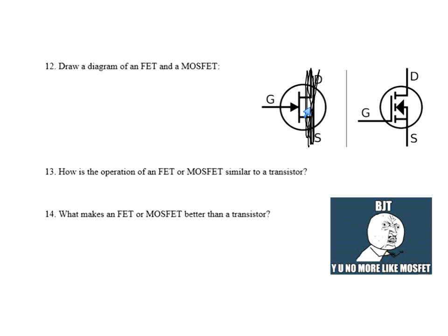And you can see that's why it's a little bit different than the BJT, because a higher voltage on the base turned it on and a lower voltage shut it off. That's the big difference between the two. Now, by using that kind of polarity, we don't need any current flowing between the gate and the source. And if you don't have any current flowing in there, it reduces the amount of heat. And that's why FETs are better. They don't have any current flowing into the gate like a BJT does, a basic transistor.